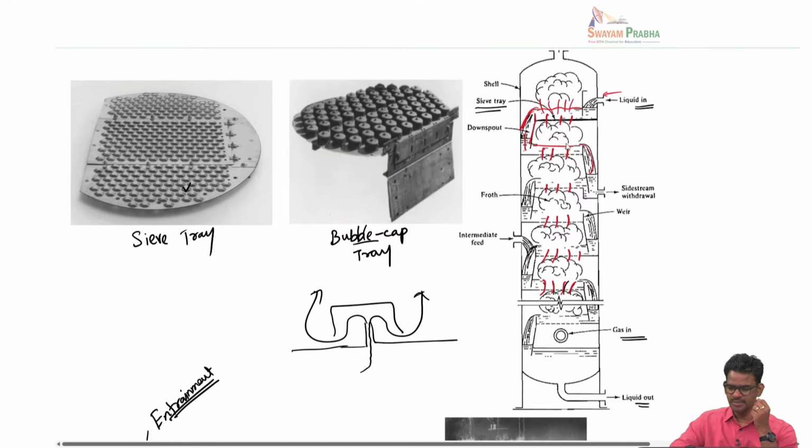Now, the interspacing with the tray depends on several things. For example, depending upon the nature of the tray, it has to be cleaned once in a while. So there should be a provision so a man can actually enter this column, do the cleaning operation and come out. So the sieve spacing is decided by considerations other than mass transfer, about maintenance, cleaning and various other things.